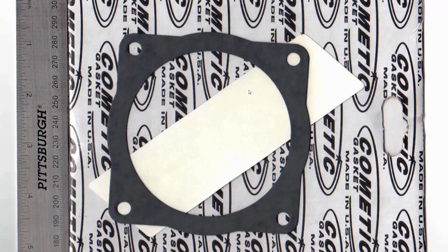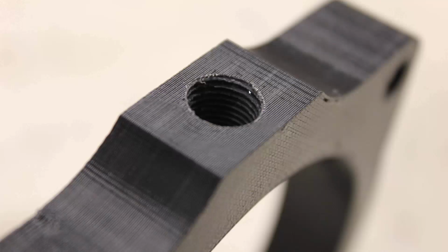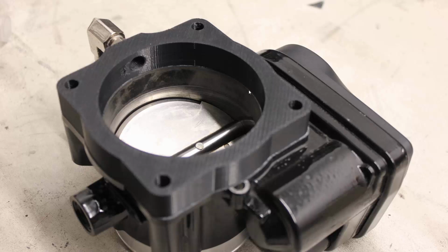Here's the part as it's printed. This is black Ultem material. There's the injection nozzle and the tap. I designed it with that through hole set to a size Q drill, which is the tap size for a 1/8-27 NPT. I tapped that, no problem. Went through like butter. Here it is sitting on the throttle body. Pretty good match. Before I go on, I wanted to talk about one thing I did within Insight.